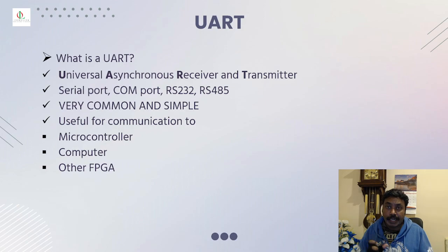When you talk about data, you have to transmit the data and you have to receive the data. That's the main purpose of the UART. And RS232, to transfer that data, can cover areas from 3 meters to 10 meters. That's roughly the basic range. But if you want to send your data over long distances, then you have to think about going to RS485. That's covered for large distances.